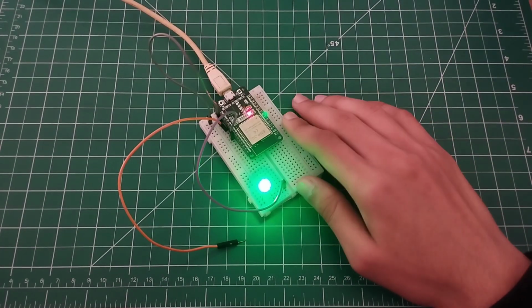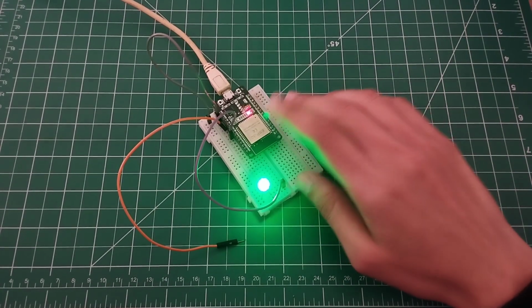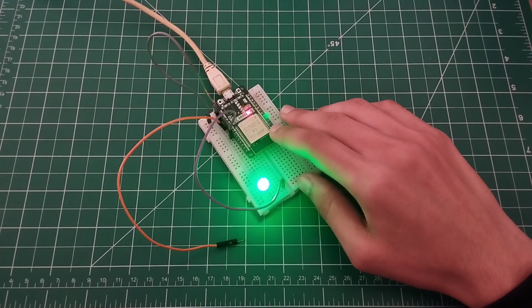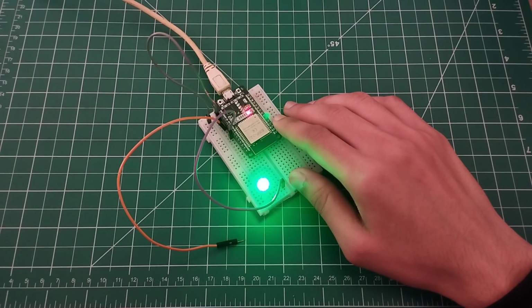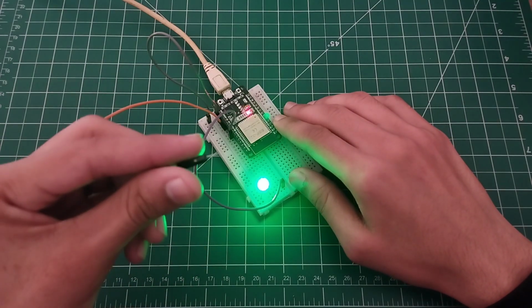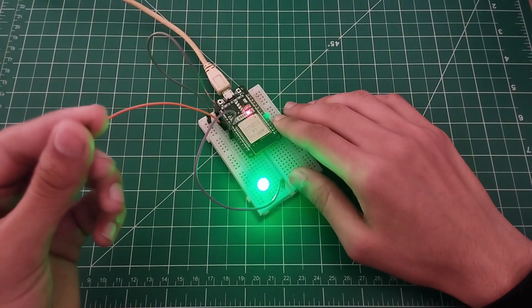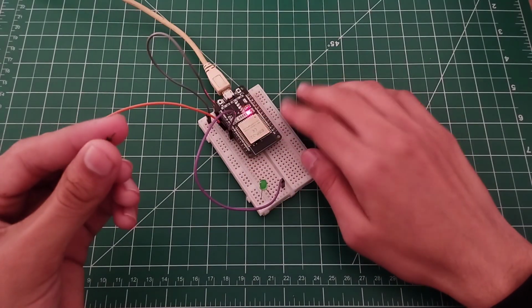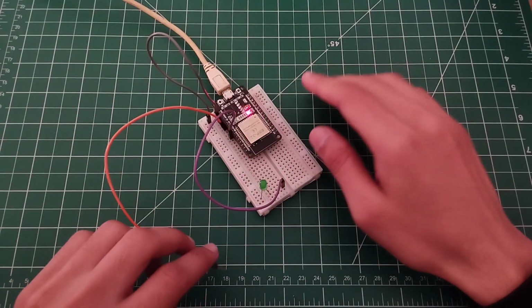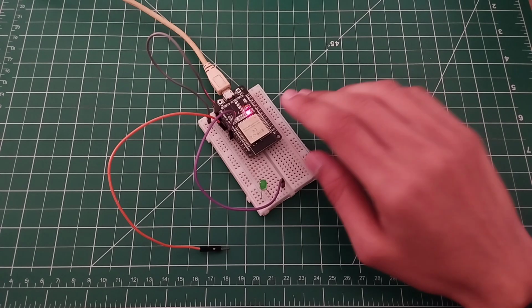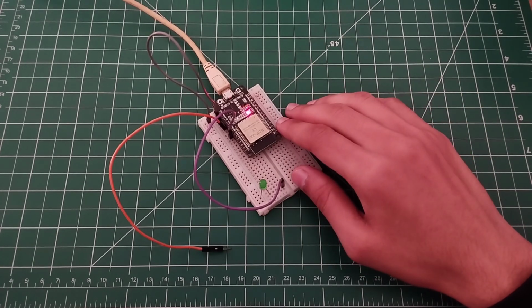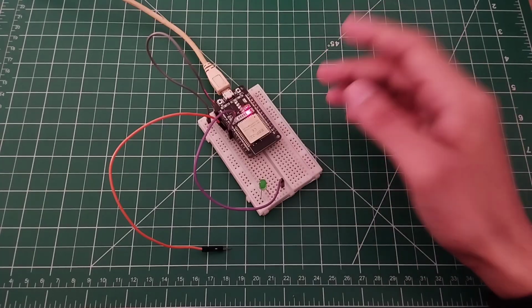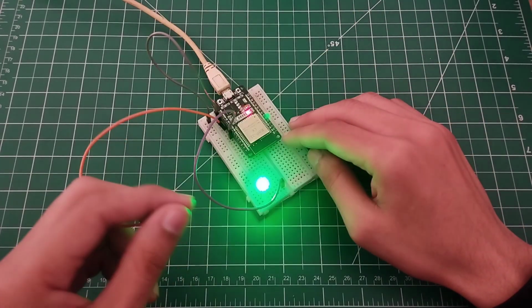Now let's understand what is actually happening in this project. So the ESP32 has a built-in capacitive touch sensor, right? And that capacitance is fixed. Our body also has some capacitance, although it is small, but definitely it has some capacitance. And when we touch this wire, we add our body's capacitance to the inbuilt capacitance of the ESP32, and the overall capacitance increases. And this microcontroller considers that change in capacitance as a number, right? And we can use that number to perform some tasks, like here we are turning the LED on and off using this wire.